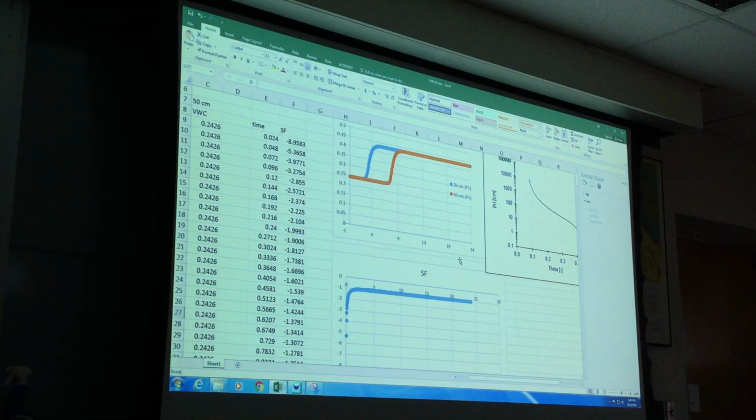saturated condition. But of course, when you infiltrate initially, when the soil is dry, you have a lot of slope. So the infiltration rate is initially high, so the flux is high. And then as the boundary layers close to the surface get wetter and wetter, it slows down. That's the reason you see the decrease in surface flux until it stabilizes. This is basically what this tells us.